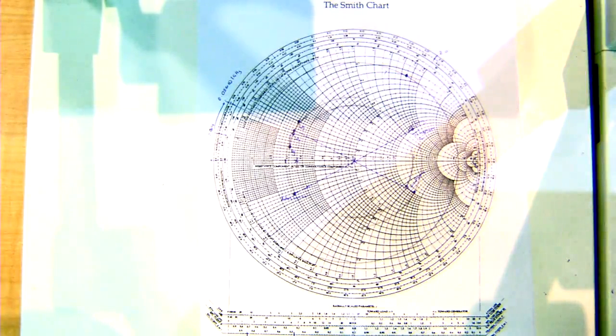Yes? How about the previous method when matching the reactance, the impedance and the capacitance? Because we didn't include the length of the... You mean the previous example where we added just J omega C? That's different. You don't have to worry about the length. But you still have to worry about the omega C, because omega C at 1 gigahertz is going to be half of what it was at 2 gigahertz. So you still have the mismatch.